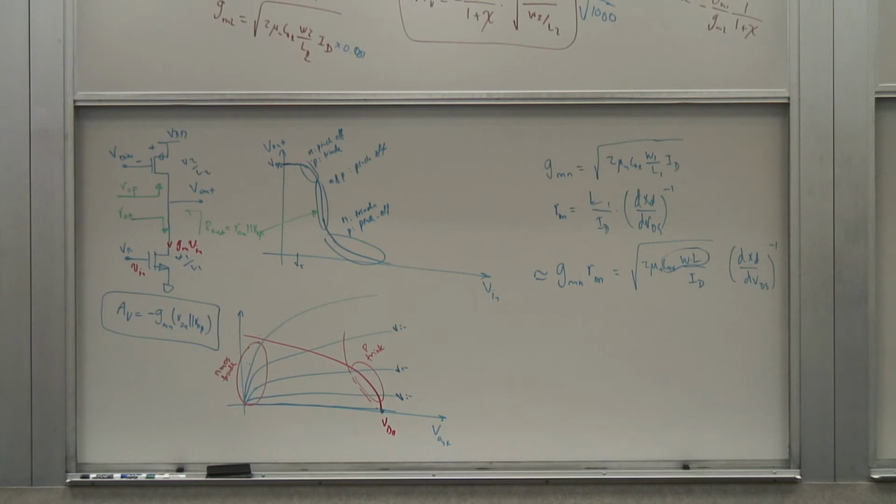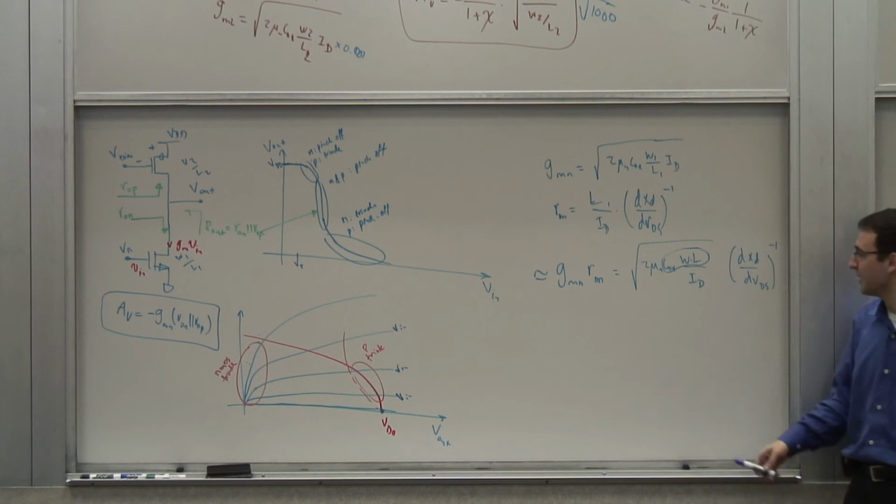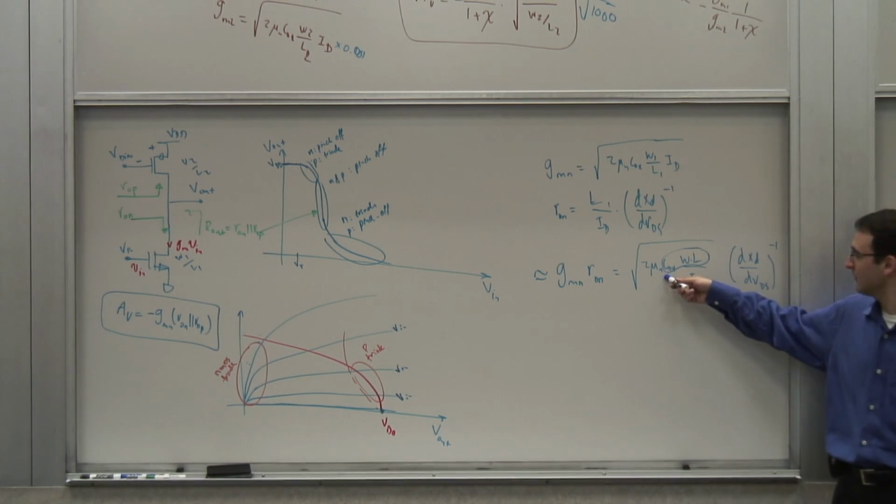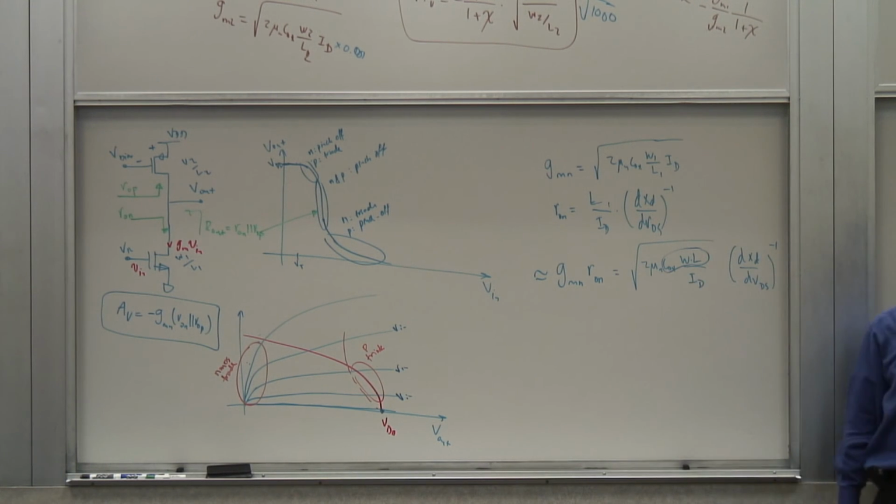Talk about gain bandwidth product, right? Or the trade-off. Talked about that last time. There's another example. You want to increase the gain, you pay for it in speed. You want to get better speed, you have to live with a lower gain for a given process technology.